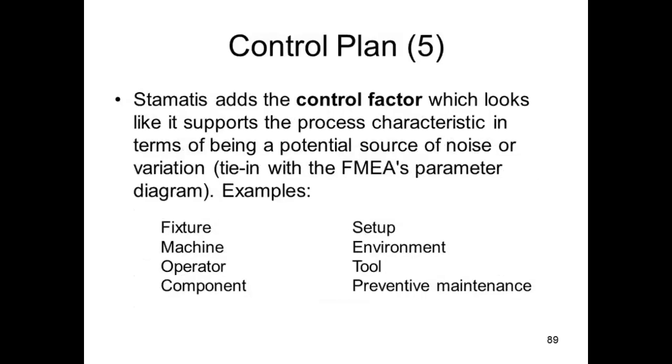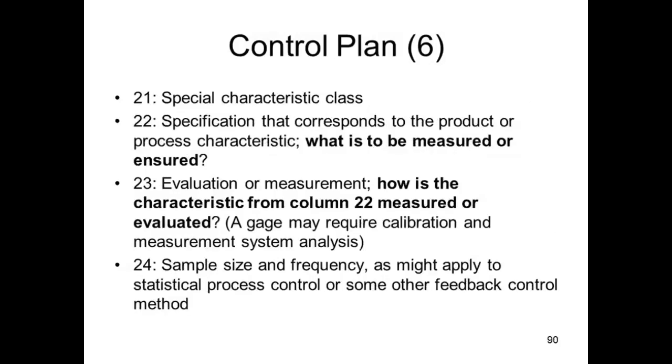Stamatis adds the control factor, I listed these before, that supports the process characteristic in terms of being a potential source of noise or variation, which ties in with the FMEA's parameter diagram. Special characteristic class, that's often automotive applications. Specification that corresponds to the product or process characteristic, what is to be measured or ensured.